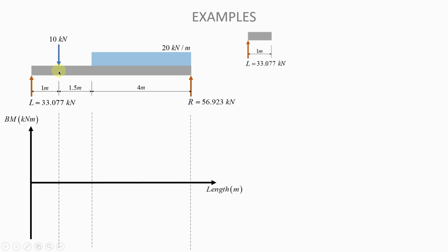And the force that is at the location of interest, of course, falls through the cut. And so this is what we will have. If we try to find the sum of moments about the cut, we only have one force, so it's only one moment. And this is a clockwise moment, so it's going to be a positive moment. And this is what you will get, just this force multiplied by that length. That is the moment about that cut.